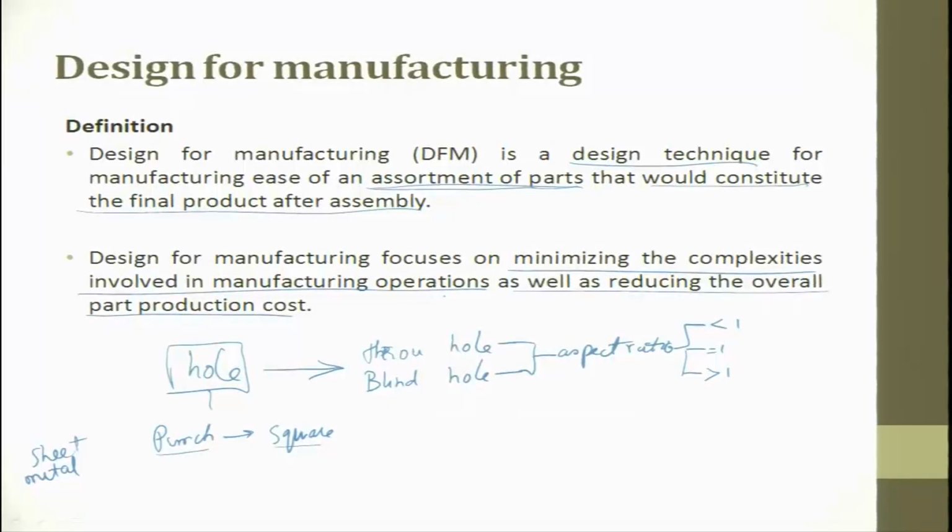It has a motor which is separate, which is a standard part, and then you have 3 or 4 jars for various applications. One with 1 liter, you can have 1.5 liters, you can have 0.25 liters, and then you can have a separate jar for the juicer. So if I do these 4 jars along with the mixie, it caters to all demands of a kitchen. So this is a modular concept wherein the complexity of the parts is reduced, and once the complexity of the parts is reduced, the manufacturing operation is reduced. The moment you make the manufacturing operation simpler, the cost is going to fall. So that is what we try to convey here.